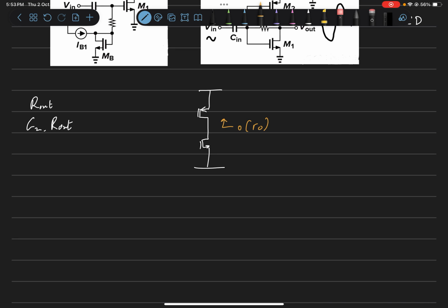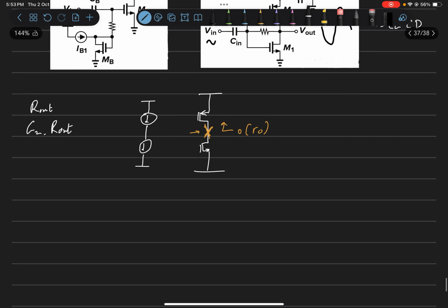Now what comes here is a very well known case of two current sources connected in series. Thus the potential here is not defined and we need to do something to set the bias at this node. So one of the commonly used techniques involves placing a resistor from the input to the output like this.